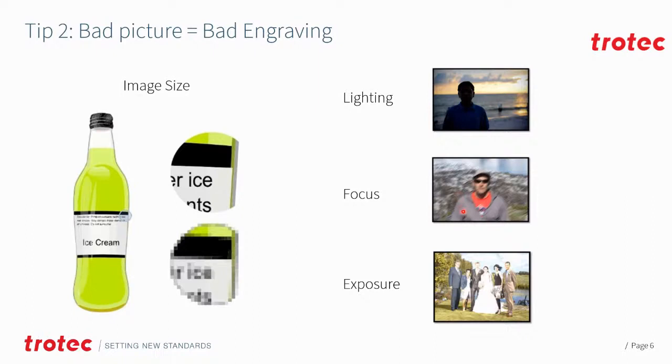And if you have an image that is out of focus, we're not going to get that definition, and therefore the image itself from the laser will of course be blurry. And again, if we have a look at exposure, we can see that this image here is quite obviously overexposed, and I would expect all of this complete region here to essentially not have much definition in it at all.